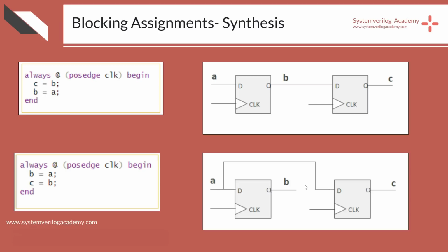When A is connected to both, in the same clock, both B and C will latch the value of A. From this description, it is clear that the order of the expressions within an always block controls the final output behavior of the circuit connections.